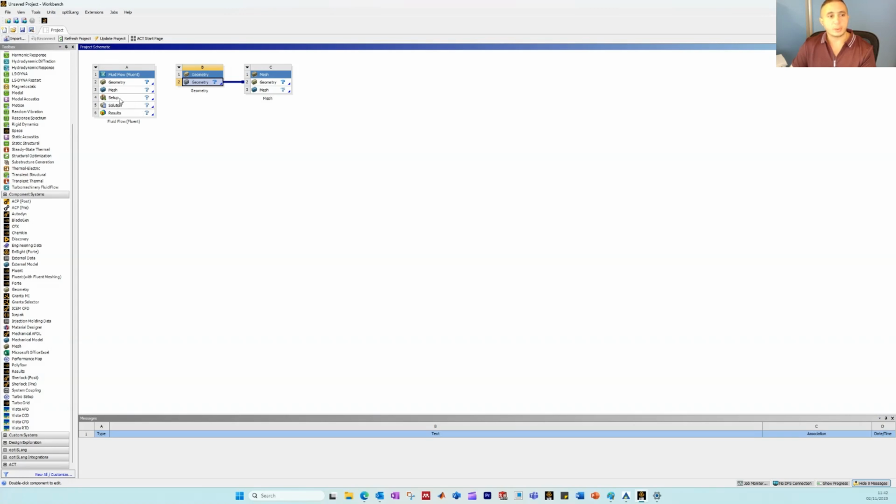Now we need to get the setup and solution, and that's from our own software, which is called Fluent, the one that we are using. Again, click, hold, drag and drop. Again, you connect the mesh itself. This is the component mesh. Connect the mesh, click, hold, drag. You cannot go to the solution here. You have to connect it only to the setup. Therefore, you let go there. Now you can see that you created exactly the same system as this one in here.